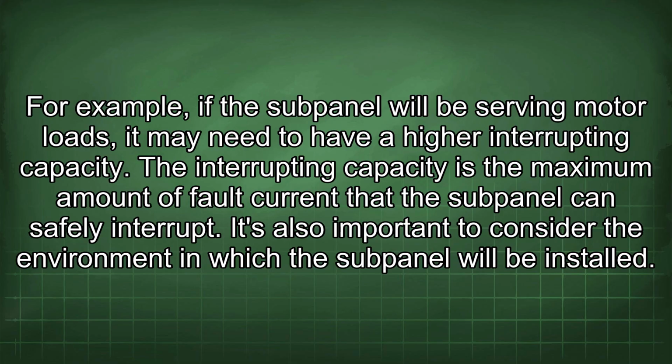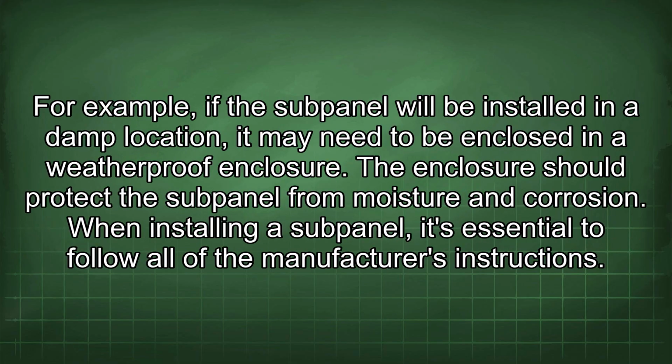It's also important to consider the environment in which the subpanel will be installed. For example, if the subpanel will be installed in a damp location, it may need to be enclosed in a weatherproof enclosure. The enclosure should protect the subpanel from moisture and corrosion.